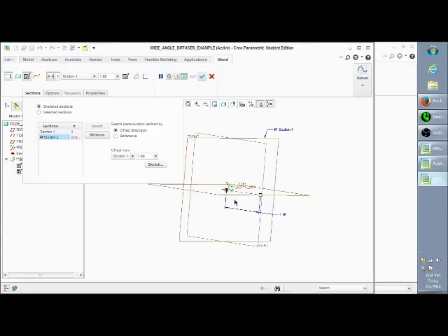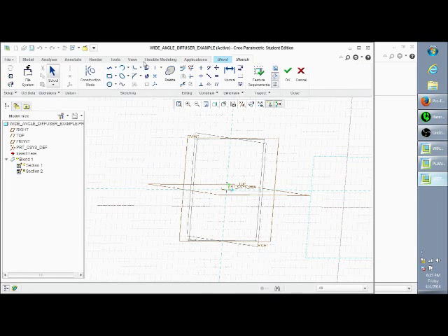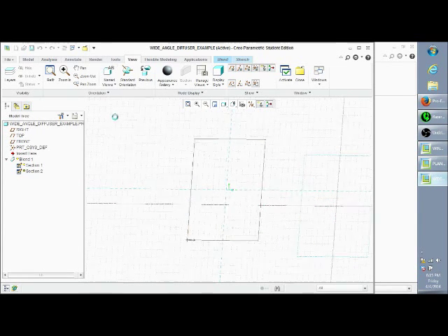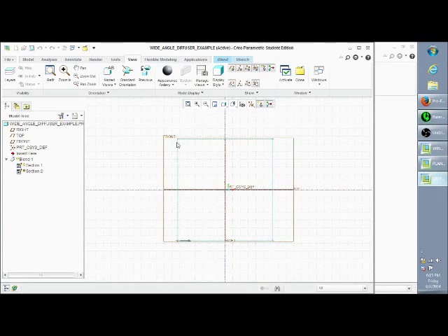So that's how far you'll extrude the protrusion out. So we're going to set that to 6.5 and then push enter. Now we can go in and sketch because it's already going into your second shape. I'm just going to put my view back to where it is. So under the view tab, go View, Front. Notice you can see your view, and you can still see where your starting point is.